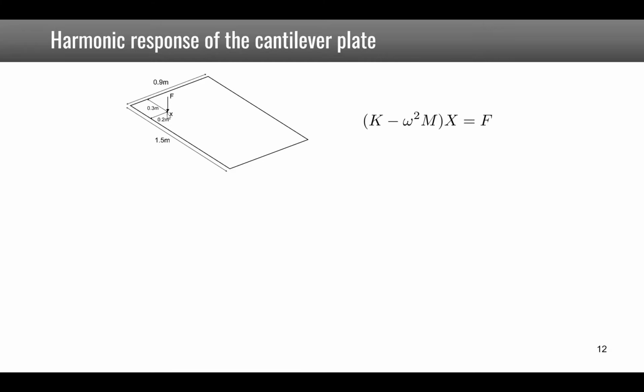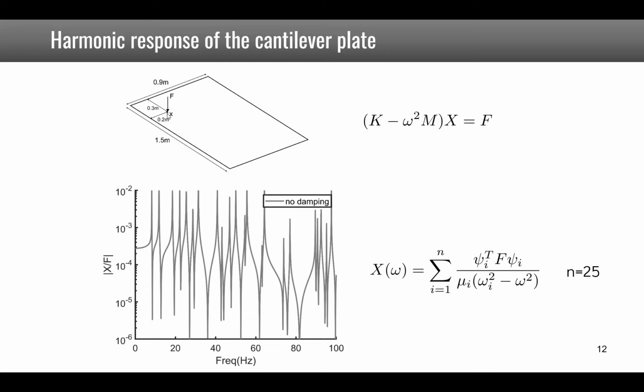So we need to solve the following problem, and after projecting in the modal basis, we find this expansion, where here we have kept 25 modes in the frequency band from 0 to 100 Hz. So we see that we have all the resonances in this frequency band, which here are not damped because we did not introduce any damping in the equation of motion.